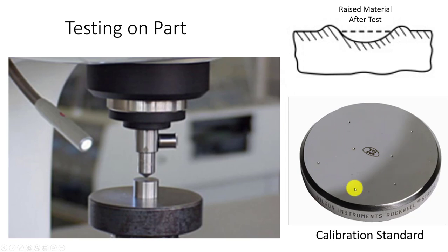These cost about $126 a pop, and after they get full, we have to pitch them. And we only take measurements on one side. So if I was going to heat treat a part, let's say I was making knives and I wanted a Rockwell C of 50 to 52, I would probably buy a calibration standard for 50. And then I would check that before I go measure my parts so that I'm closing the gap and not having a calibration standard that's way off. And that becomes part of my ISO procedure possibly.